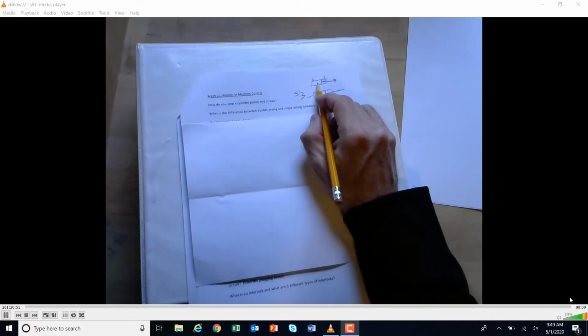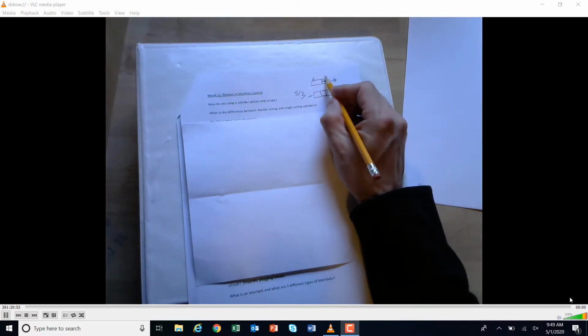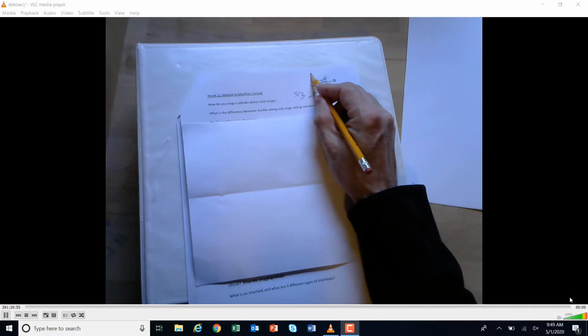The benefit of the double-acting is that you can get a lot more force here, and you can also get force here, a lot of force to push and pull that. Whereas if you don't have this one, you're relying on the spring, and if the spring isn't strong enough to pull this back, if it binds or something, then this gets bound and is extended, okay?